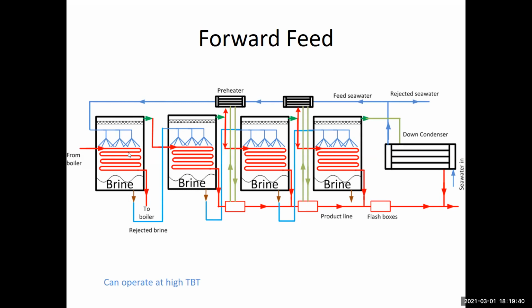First effect is receiving steam from an external source, a boiler or a power plant. So after condensing, the steam should go back to that source. Whereas starting from the condensate in effect number 2, this is our product. The vapor that we are getting here is the vapor that has formed in effect number 1.